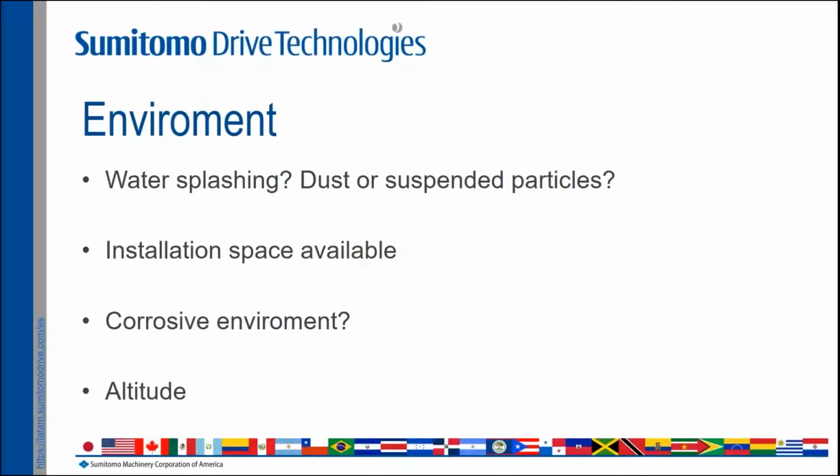But also you need to take into account the environment. What happens if in the site where I will install my drive, there is water splashing, or maybe there's a lot of dust particles or another material that is suspended in the air? Also, I need to know how much space I have available for the drive.